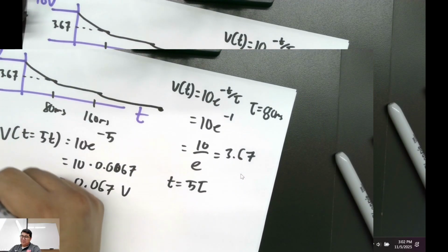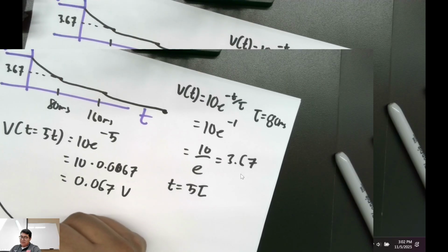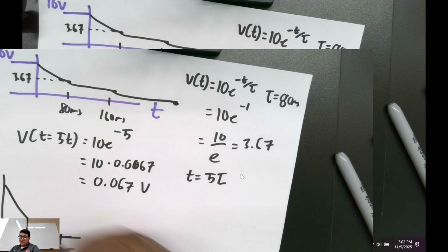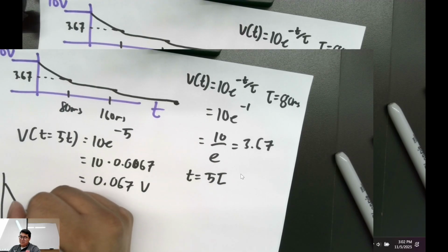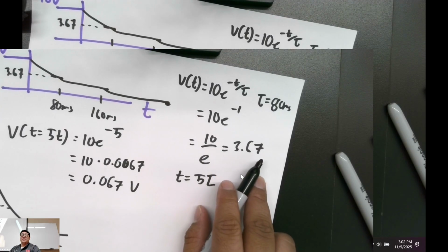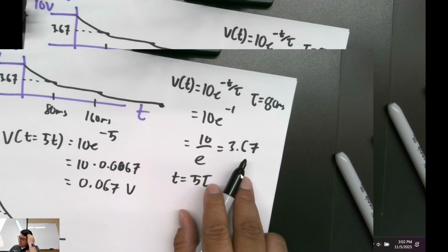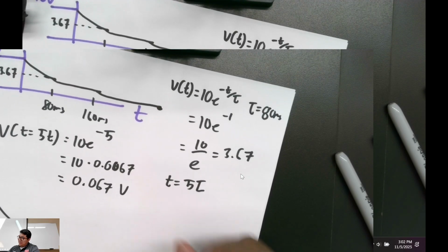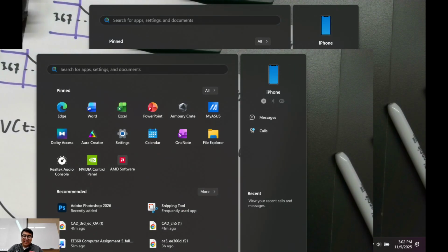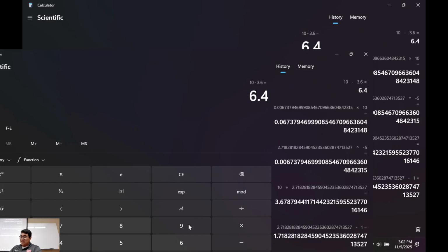So you guys see this exponential? If I were to just draw it simple, like that, after 5 time constants it looks like it's just 0, it's discharged, right? But after the first time constant, we lose almost 60-something percent. Is that good with everybody? Actually, what is this right here? 10 minus 3.6 is equal to, where's my calculator? 10 minus 3.6. Yeah, 64%.